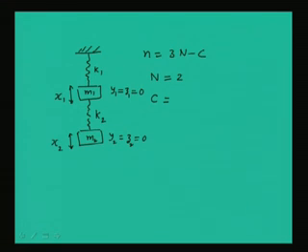So, a total of 2 plus 2, 4 constraints are there in the problem. So, the number of degrees of freedom can be obtained as 3 into 2 minus 4. So, that will give us 2 degrees of freedom. So, you can see that to define the motion of mass m1 and m2, we require two independent variables x1 and x2, and that is the degree of freedom of the system.